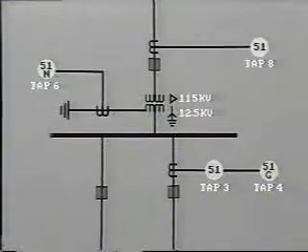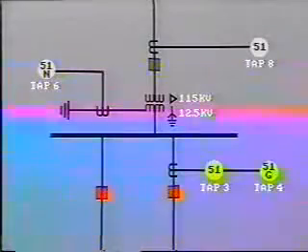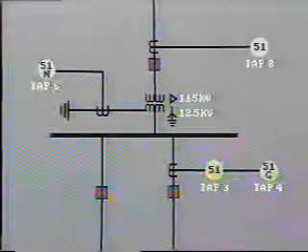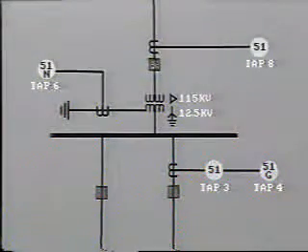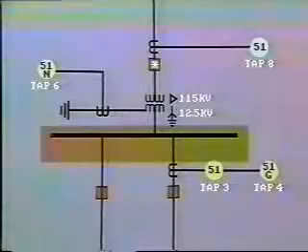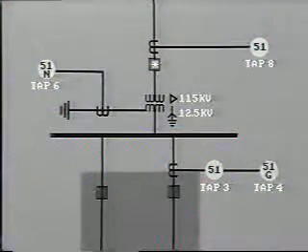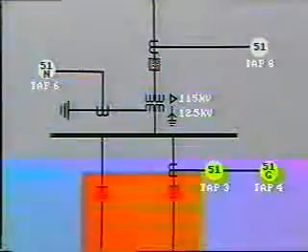Another arrangement here shows a circuit breaker on the primary with the secondary connected directly to a bus. Each feeder has its own circuit breaker and individual protection. The primary circuit breaker will trip for a fault in the transformer zone, or a fault on the bus, or a fault on any feeder which fails to be cleared by its own primary protection.